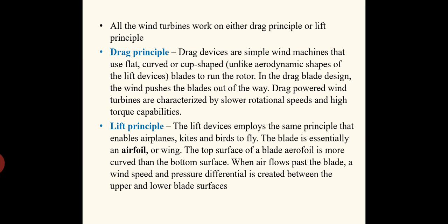Now coming to the lift principle, lift devices employ the same principle that enables airplanes, kites and birds to fly. Everything is using the same lift principle to fly. The blade is essentially an airfoil or wing. We will generally call it a wing. The top surface of the blade airfoil is more curved than the bottom surface. When the air flows past the blade, a wind speed and pressure difference is created between the upper and lower blade surfaces. This will create the lift force. We have already discussed this principle.